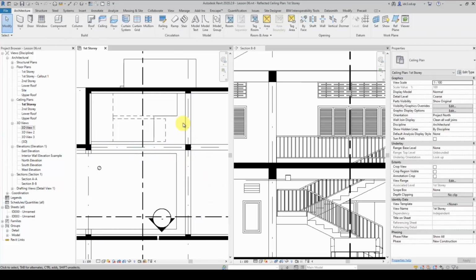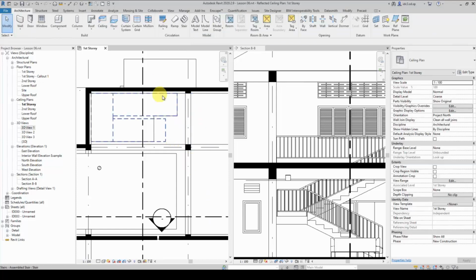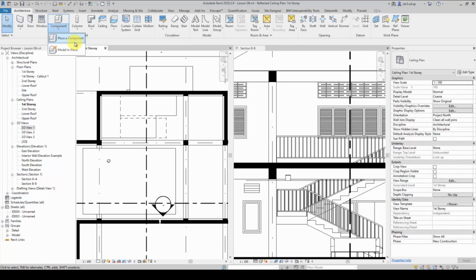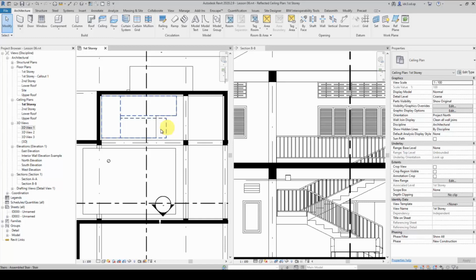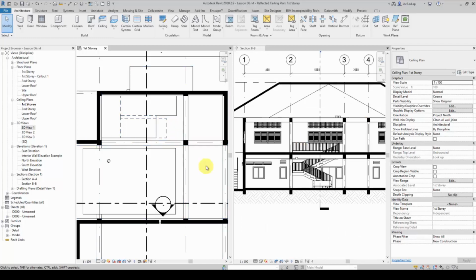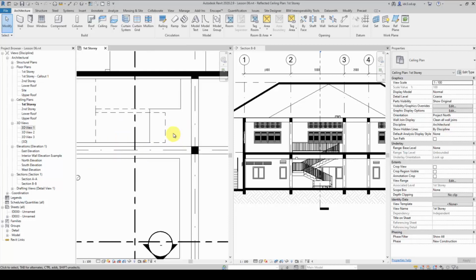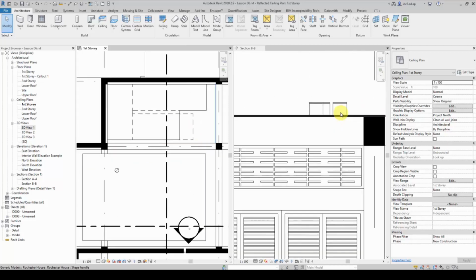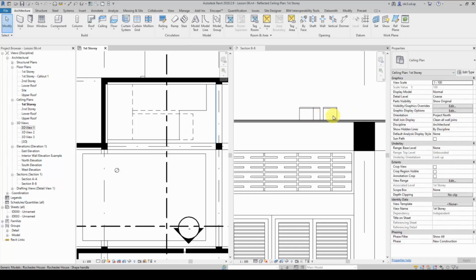You may want to check the active view, its parameters, and visibility settings, as well as any plan regions and their settings. All right, so it's quite a mouthful here, but in fact, it's telling you, hey, wrong elevation or wrong view. Please pay attention to this. So again, when I create ceiling elements, there is always this tendency of us setting it wrongly, or depending on how we download this model, or who created this additional component that we download from.